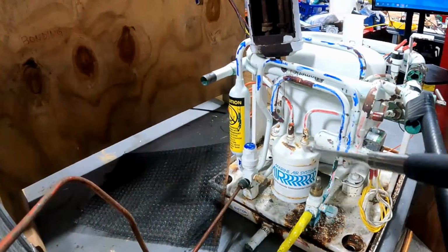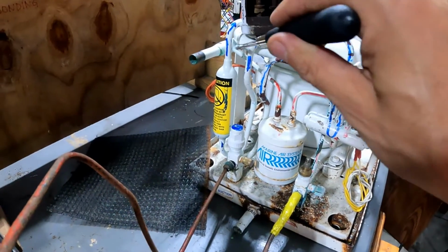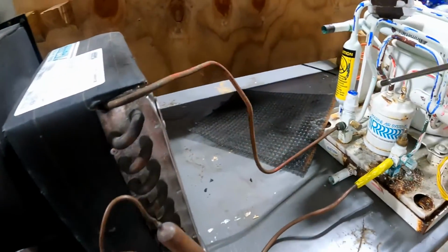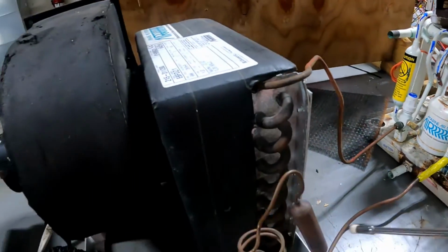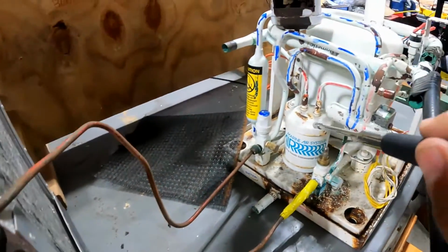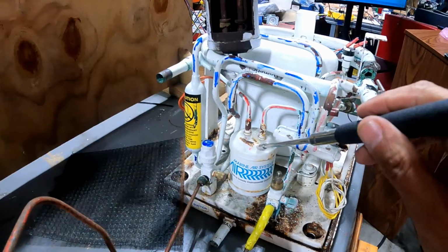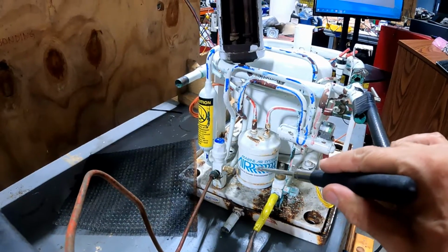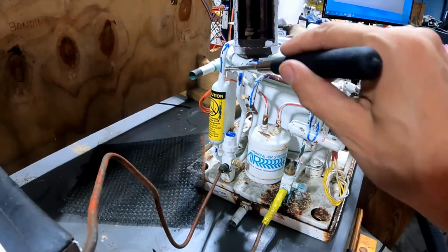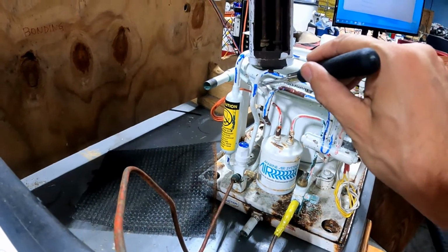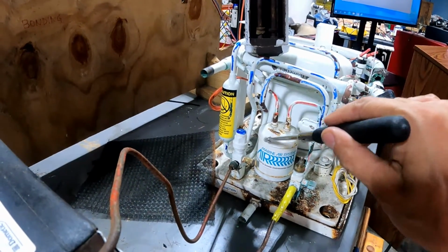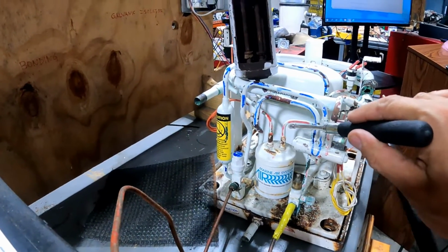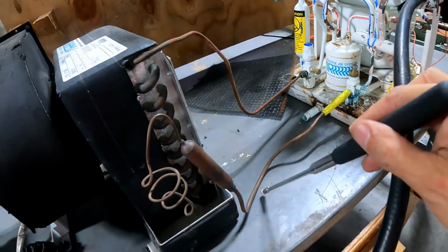For that reason, the receiver dryer is located in between the output of the compressor and the expansion valve. And the function is to absorb humidity, absorb moisture, and start the process of condensation, because just at the output of the coil it is vapor, but after that, when the refrigerant enters the receiver, in the output it is liquid, and continues as liquid at high pressure and high temperature.